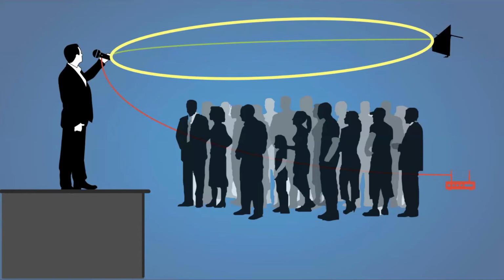Likewise, if you had your antenna so close to the ceiling, then the ceiling is going to be inside that first order Fresnel zone. So just in really big rough numbers, if this distance represented 100 feet, the Fresnel zone, and it changes with frequency, but somewhere in the mid-band UHF is basically going to have a radius of about 7 feet. That's why we want you to get antennas up over head height, but they need to be a little higher than that because we don't want any bad reflections. We don't want to lose any more power just because we put our antenna 2 feet too low.